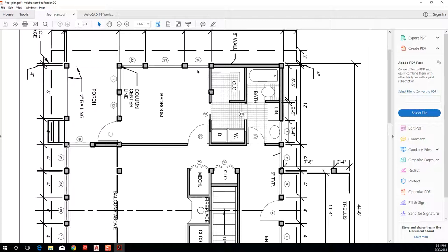Those really important architectural elements, okay? Those architectural elements, the cut line will cut those important pieces, and those important pieces are given a heavy line weight, right? As I go from that 3 foot tall cut and I look down, I'm also going to see those elements, right? And in my field of vision, the things that are cut are going to be the heaviest pen weight, and of course they have the most importance.